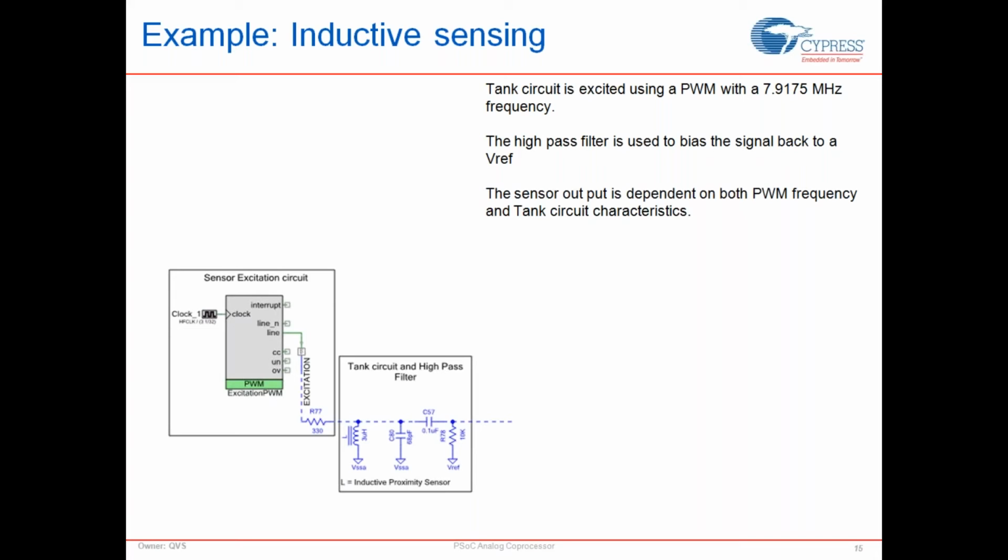So we're going to have a PWM built using a fractional divider, which is a mode of the input clock dividers where you can configure them for fractional division. In this case, it's a divider of 3 and 1/32, which means 1 out of 32 phases of the clock output, I'm going to have 1/3 of the divider, and the rest of the 31 phases, I'm going to have 4/3 of the.